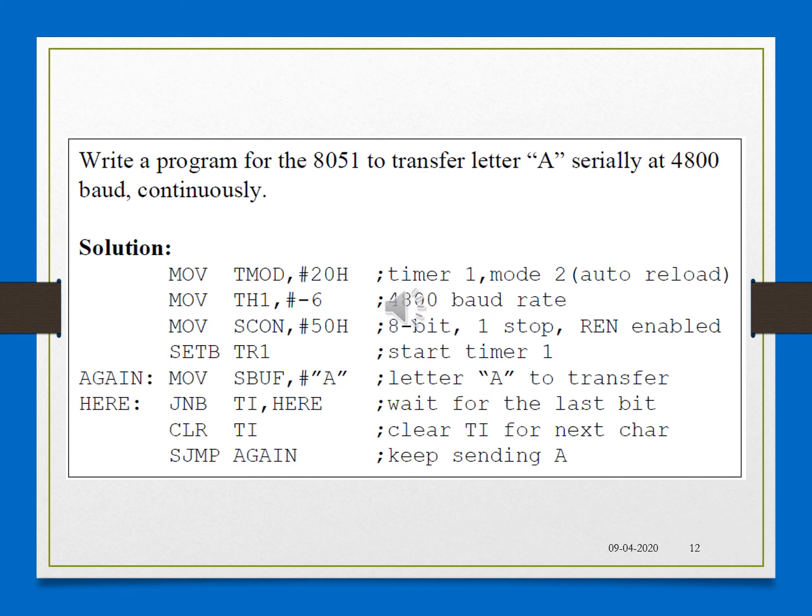It is 0101 0000. That means in the lower nibble, RI, TI, RB8, TB8 are all zeros. TB8 and RB8 are not used here, because they are used only in mode 2 and mode 3 of serial communication. We are discussing only mode 1 of serial communication.